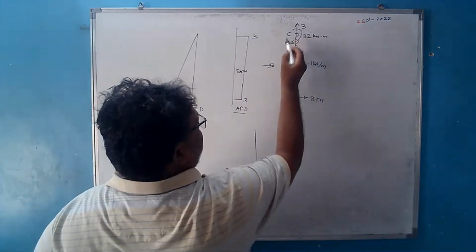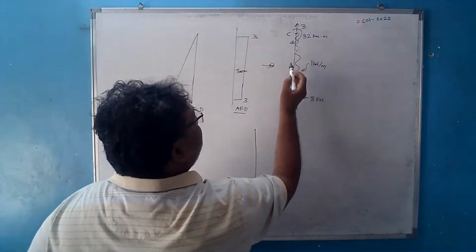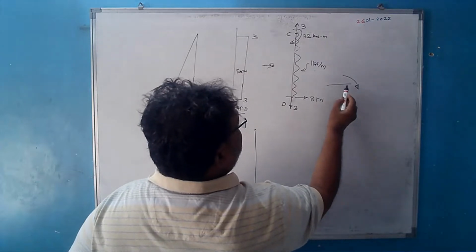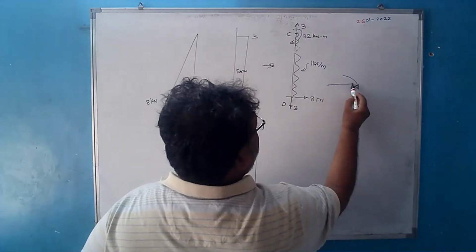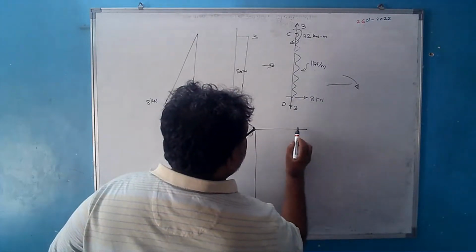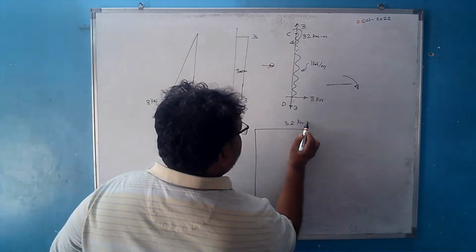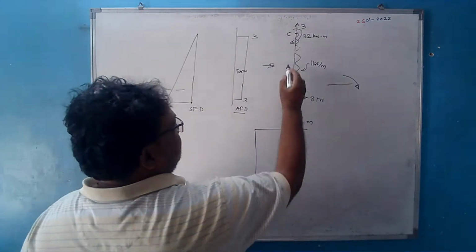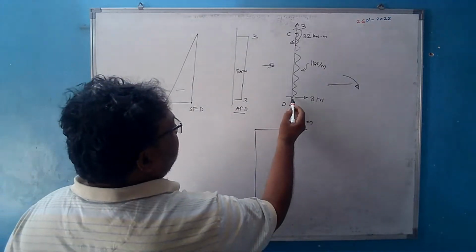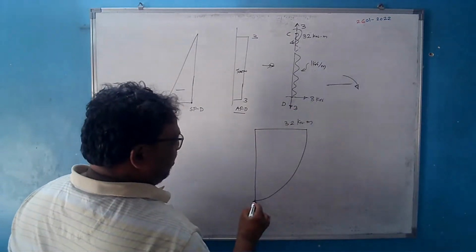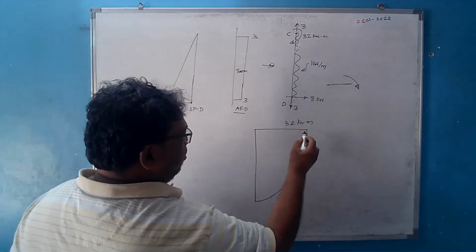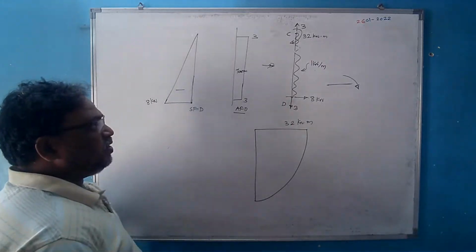Look here, the bending moment is 0 just at the joint, but if you see this couple, this is how the moment is acting here. So this moment is acting positive, right? So the bending moment here will be 32 kilonewton meter. As we come down, the bending moment will keep on reducing. There is no moment here, so the bending moment here must be 0. And as it is because of the uniformly distributed load, the bending moment variation must be a parabola.